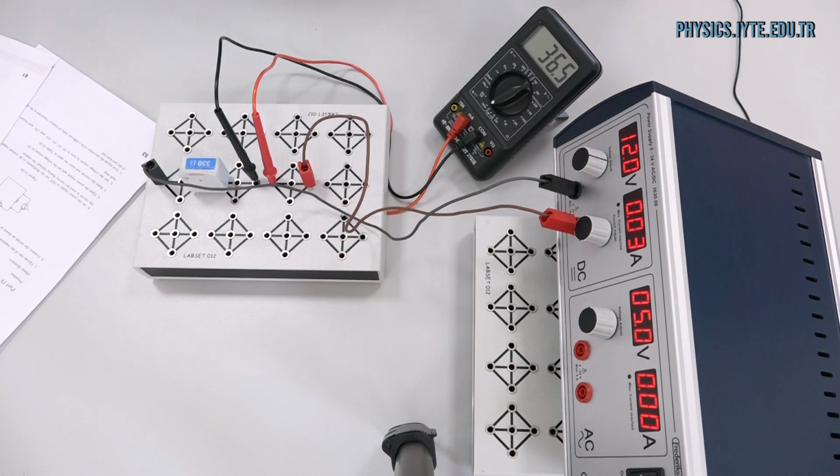Next, we will analyze this data and we will find the resistance value of this resistor by plotting the resulting current versus applied voltage, and the slope of this graph is going to give us the inverse resistance value. We ideally use ohmic resistors. For ohmic resistors, we expect to see a linear relationship between the current and voltage.